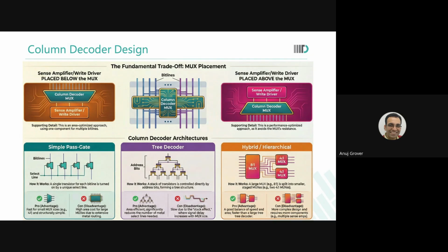So the limitations that we talked about for the pass gate or transmission gate logic are not existing over here at all. Are you with me? And if you also have to design a multi-VT design, if you have the flexibility to use multiple VTs in your design, the SRAM cell array, you will always use HVT. Okay?